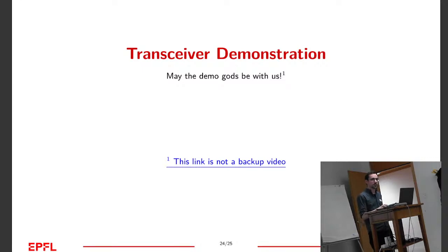Yes. So a receiver will have, depending on the spreading factors, so the chirps have different slopes, that's a parameter that you can use. So the receiver needs to listen to all spreading factors and all the channels that are interesting. So that makes a lot of receivers in parallel. Maybe 64 in a gateway.